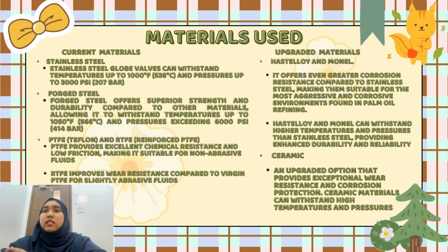Second is ceramic. Ceramic globe valve components such as the disc and seat are an upgraded option that provides exceptional wear resistance and corrosion protection. Ceramic materials can withstand high temperatures and pressures while maintaining their integrity, making them ideal for demanding oil refining applications.